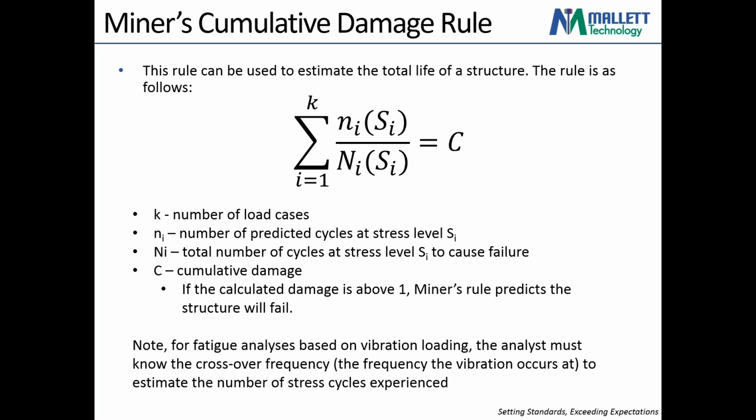Okay, and so the one note here is that if you're looking at fatigue analyses based on vibration loading, the one piece of information you need to know as well is the frequency at which that vibration occurs, right? It's called the crossover frequency, and knowing that will allow you to calculate this small n value, the number of predicted cycles.